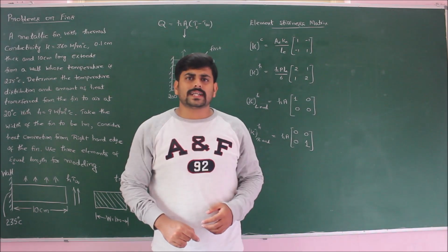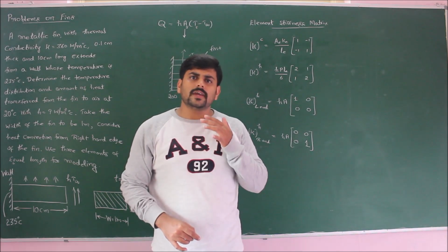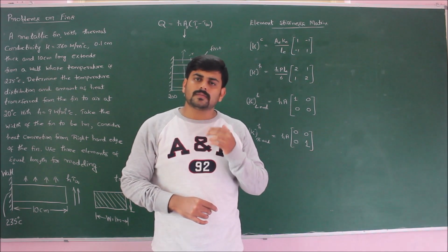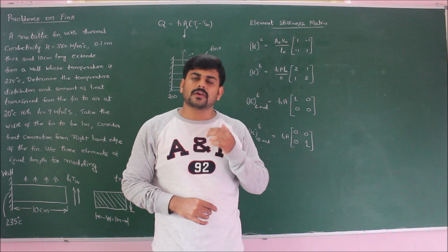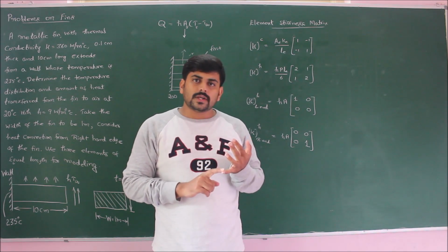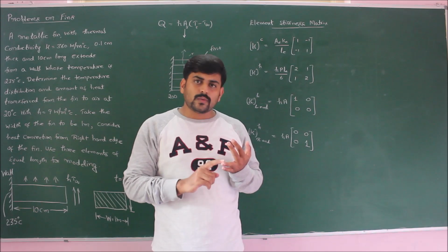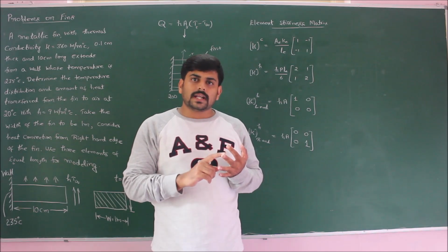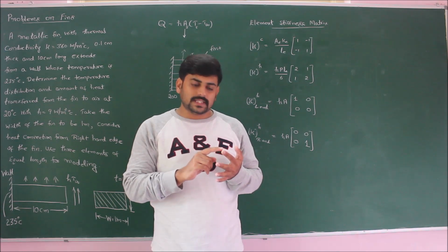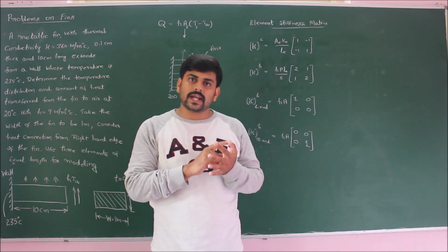Coming to the load vector, as we already discussed, all the 5 load vectors should be known to solve problems on analysis of extended surfaces or fins for heat transfer. One is the load vector due to internal heat generation, load vector due to flux, load vector due to surface convection, load vector due to right end convection and load vector due to left end convection.